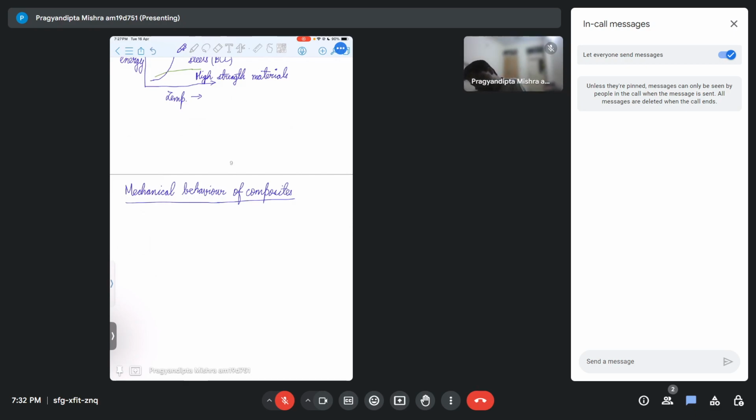Okay. Now why is this bonding important? For strain continuity, right? Because of the strain, you should not see the bonds break and then the entire system split into two halves or something like that, right? So you should not see some breaking happening. So for strain continuity, the bonding should be well done, and that is being ensured by the reinforcement.